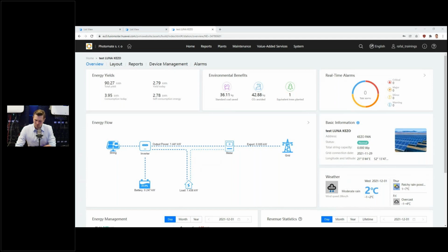Yes, one should always basically consider the smart logger or dongle as the brain of the system. I will just tell you one interesting thing. Officially, if you have read any materials from Huawei, we don't support communication by WLAN or Fast Ethernet dongle for inverters like 60 and 50 and 100. But unofficially, I can tell you that you can easily use those dongles, I mean, WLAN or Fast Ethernet, for those inverters.